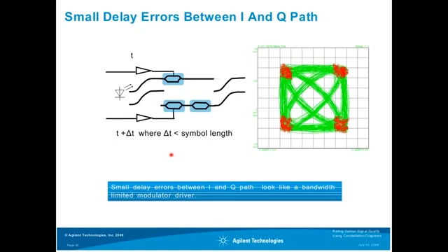We can even think that a different bandwidth causes different group delay, and the group delay implies that there is a different traveling time between these two paths, and this indeed is exactly a difference in the symbol positioning of these signals.